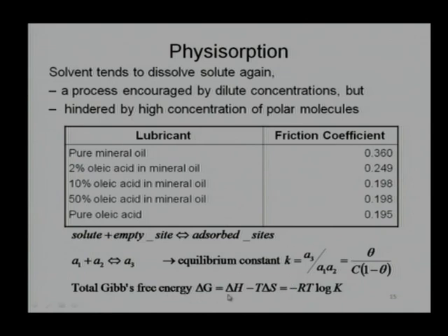Gibbs free energy, we can say, is more like a potential energy of the surface of a material. That much energy is required to distort the surface, to move the surface or to change its position. So, it shows how much energy we require to change the position, and it clearly depends on the temperature. If the temperature is increasing, this term will increase in magnitude and it is a subtraction, that means the Gibbs energy will reduce, and we require less energy to disturb the equilibrium. Otherwise, if the temperature is reducing, we require more energy to disturb the equilibrium.